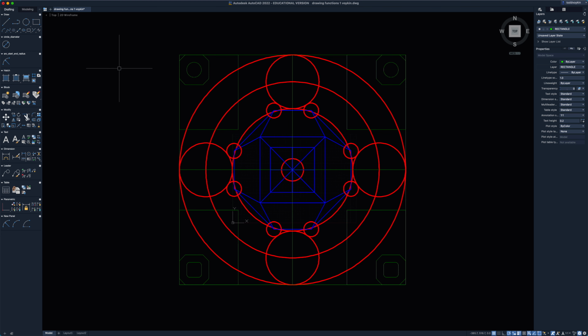Okay, so let's head up into our tool sets on the left-hand side. And now if I left click on the rectangle right there and I go down to its second selection right there is Polygon and release, it's now saying how many sides do you want? I want 12. And where are we starting it from? From the center of this object. And now it says, do you want it inscribed in the circle or outside the circle? And our instructions said inside the circle.